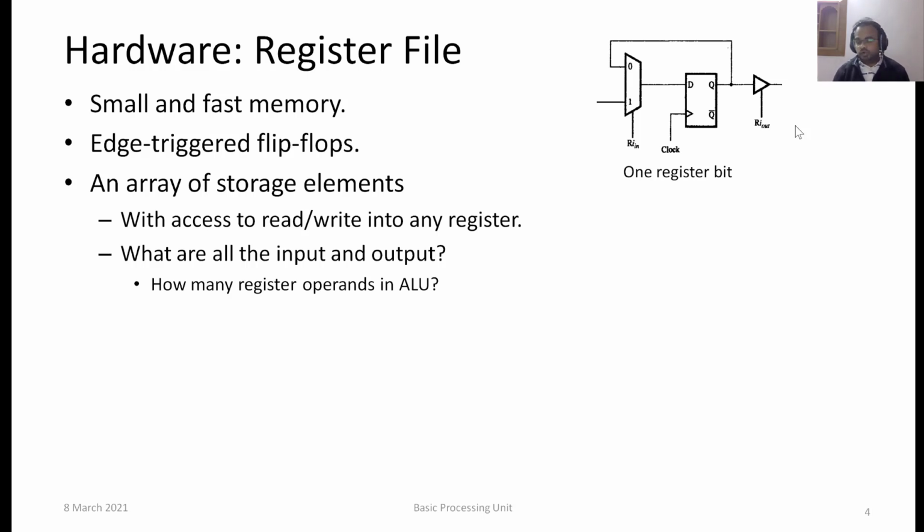And will this hold for other instructions also? If we look at how many register operands there are in a load instruction, it is 1 source register and 1 destination register. And when it comes to the store, both the registers are source registers. For control instructions, for branches, we would read 2 registers, and for the jump instruction JALR, we would read 1 register and write to 1 register. For JAL, we simply write to 1 register, right?